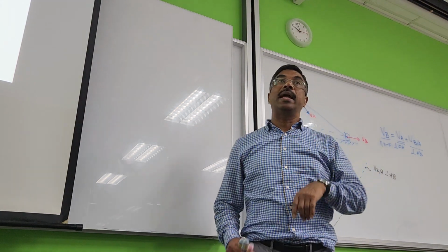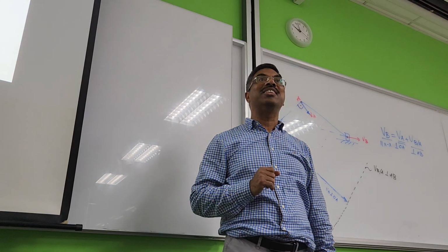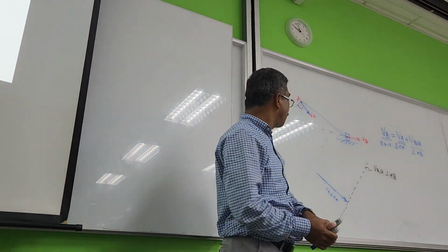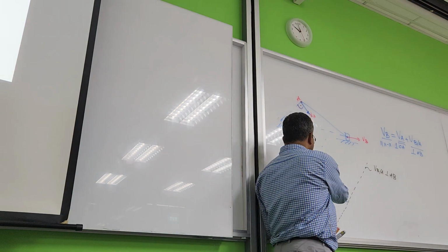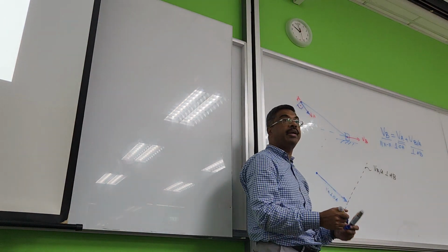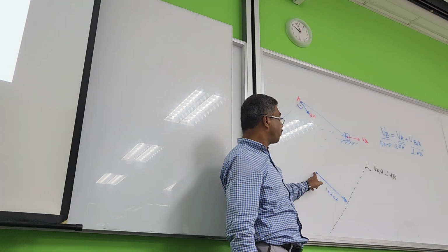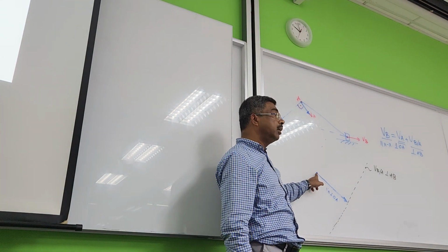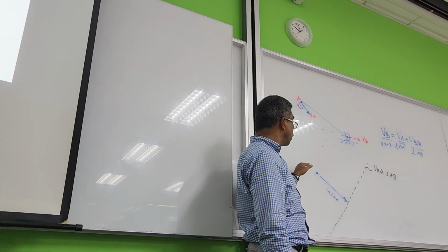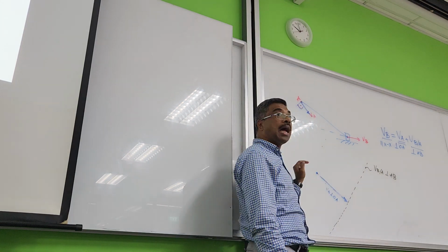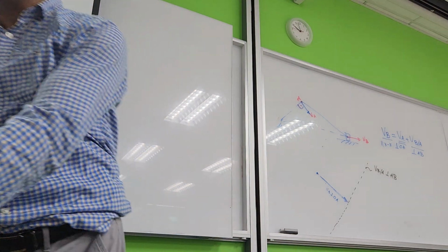But we need to look at our V_B. It's the velocity of a link that has a connection with ground. Therefore, it should start from where? From the origin. And the origin you always mark with a little circle, so that you know where it started. So now our V_B should start from the origin, but from the origin it can go to the right, it can go to the left. But how will it be going? Parallel to the horizontal direction.